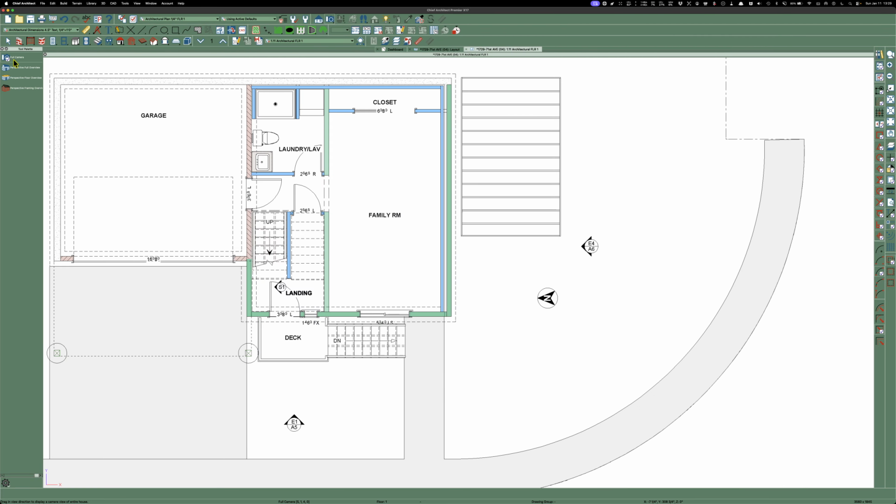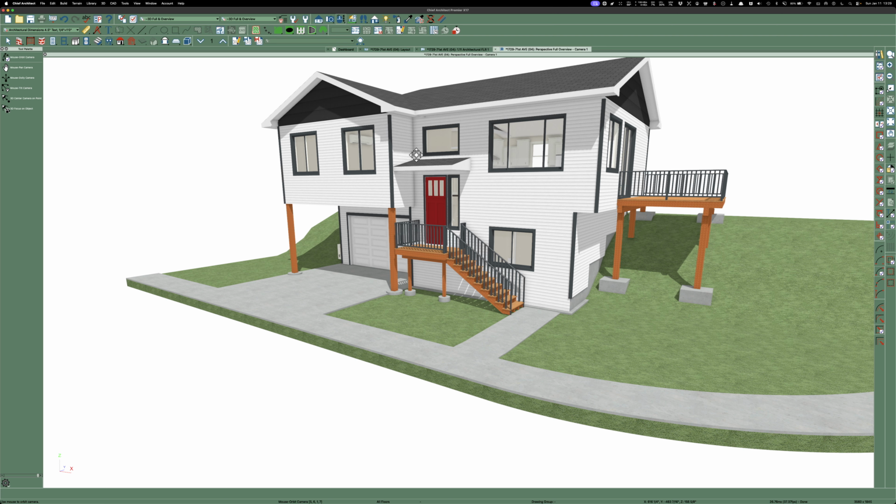So from right around here, I had to balloon frame everything so that the door would cut through where the top and bottom plates are, because you don't want to run 2 stories up with walls that are stacked on each other, because that's another hinge point where it becomes weak.